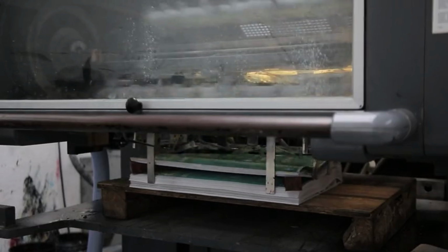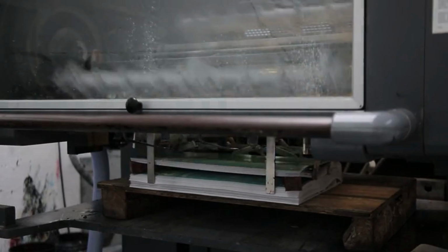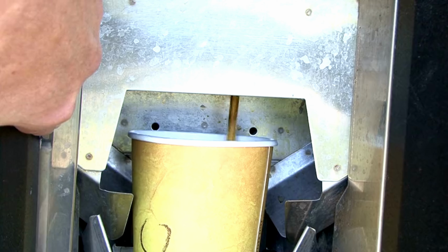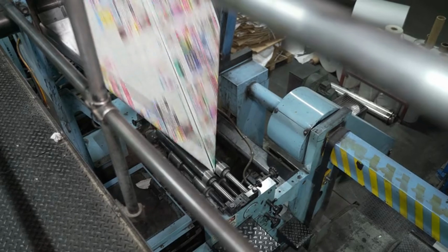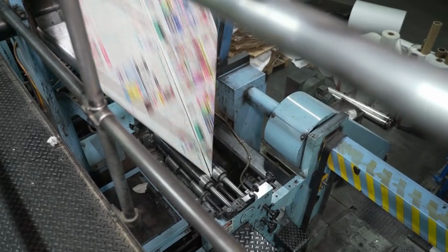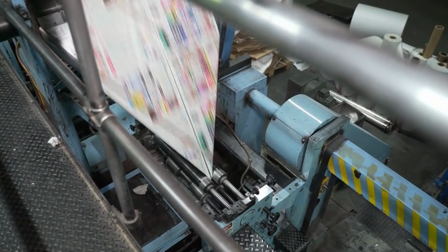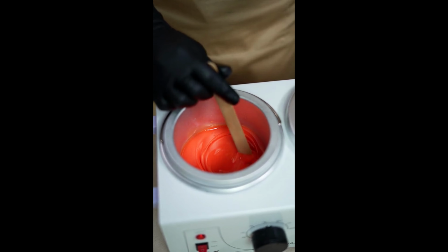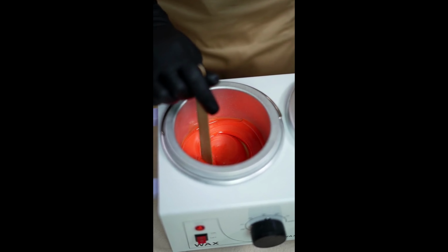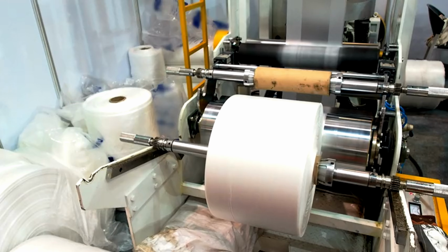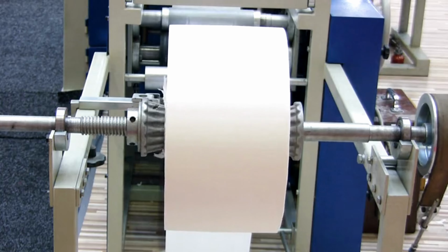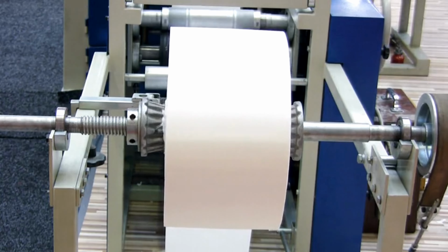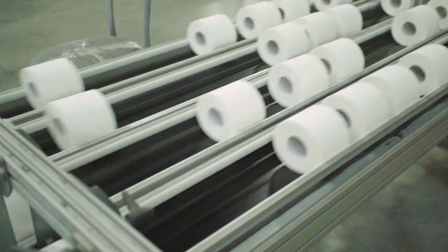6. Pressing and drying. The wet sheet passes through rollers to squeeze out more water. It then moves through heated drying cylinders to evaporate moisture. 7. Calendering and finishing. The dried paper is pressed between smooth rollers, calenders, to improve texture and thickness. Surface coatings, for example, gloss, matte, may be applied for specific finishes. 8. Reeling and cutting. The finished paper is wound into large rolls. These rolls are cut into smaller sizes depending on the intended use, for example, printing paper, packaging, newspapers.